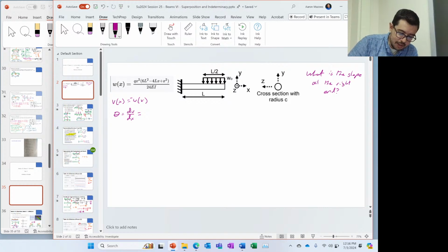Now the theta, unfortunately, is kind of tedious, but it's not too bad, and we can write it out as this, where we have the 2, and they're using q. We'll use w naught, but this is only being applied halfway across, whereas the table is giving us information across the whole span. So we can use q. It's fine, we'll just use q. So qx, and then this quantity.